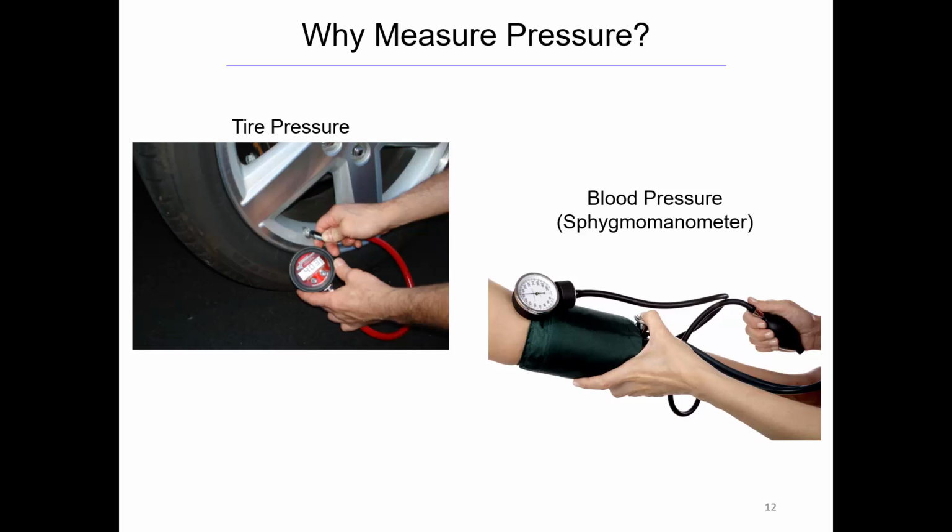And they'll have one of those on each of the wheels. If a wheel is spinning faster than one of the others, it means it's lost pressure and it's gotten smaller. So it'll need to spin faster to keep up with the others. That minute change is something the computer can detect and say, hey, that tire's likely got too low of pressure. That type of system is a lot less common than the ones with just this little module here that has a piezo element in it.